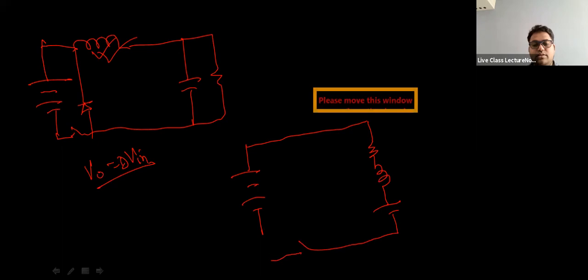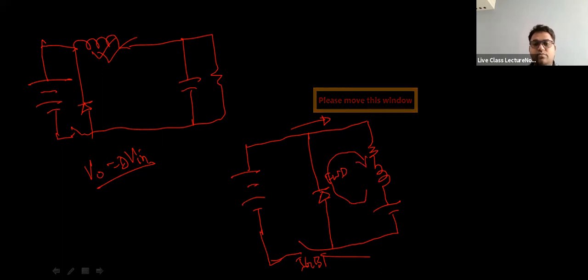And this is the switch, that is the IGBT, and this is the freewheeling diode, right? If you turn it on, power will start to flow through the motor. If you turn it off, it will circulate through the freewheeling diode. And you may or may not put a capacitor also. It's better not to put a capacitor, as that will have an additional cost.